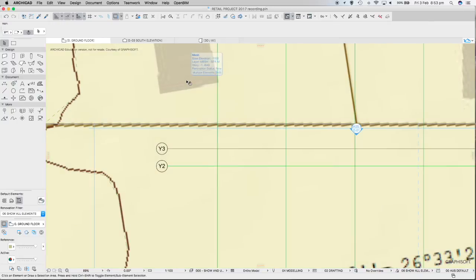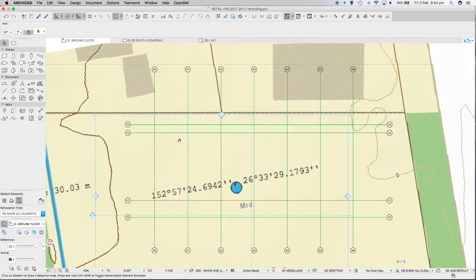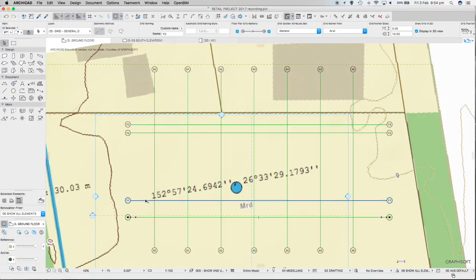Okay, now we're back to where we should be, although there's probably one other thing I need everybody to do. If you've got those grid lines in place, even if you had them from before, let's all go into the ground floor plan, because I want to set them all up so they're at a convenient level for visualizing what's going on. So I want to select all of the grids, so do a shift select, so we get all of them selected at one time, just the grids, across this direction too.